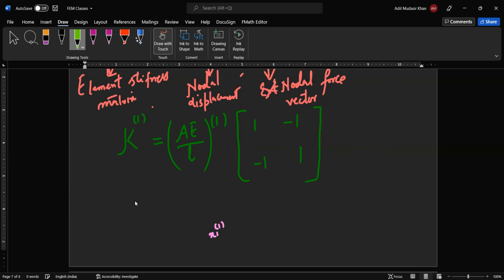And how do we write the force vector? Ka minus F is equal to Q. F is equal to L T by 2 for element 1 multiplied by 1 1, written in curly brackets. This is the matrix representation of our equations. This is our K, this is our F. Fine. Now this is very simple, very much equivalent to what we have already done.